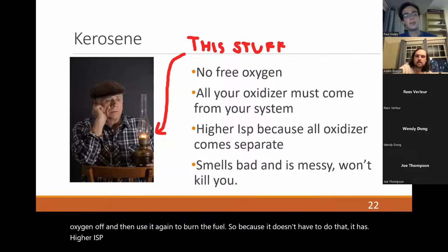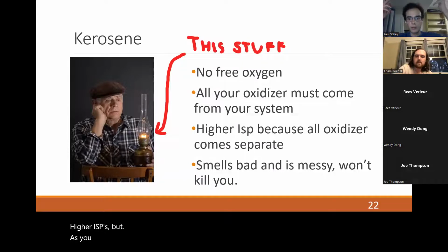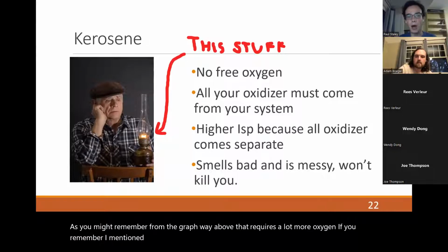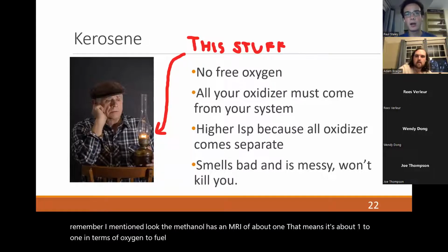But as you might remember from the graph way above, that requires a lot more oxygen. If you remember, I mentioned, oh, look, the methanol has an MR of about 1. That means it's about 1-to-1 in terms of oxygen to fuel, whereas the kerosene had an MR of around 2, which means you need twice as much oxygen, and that's largely...